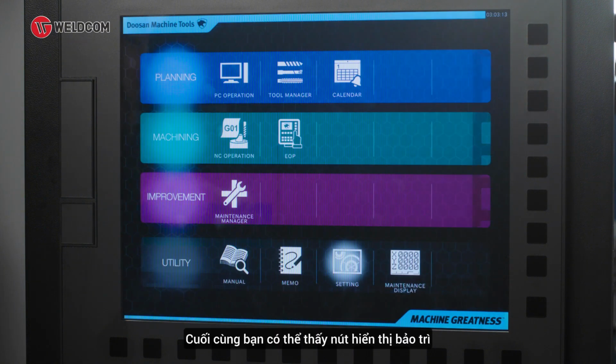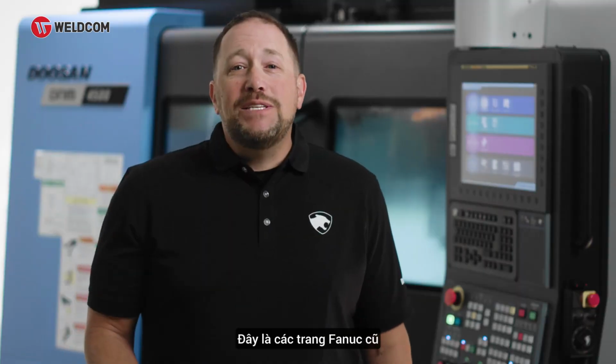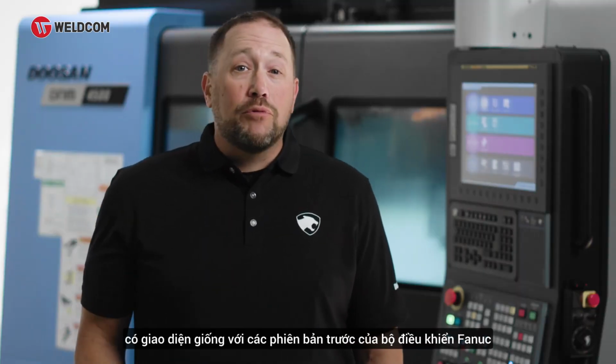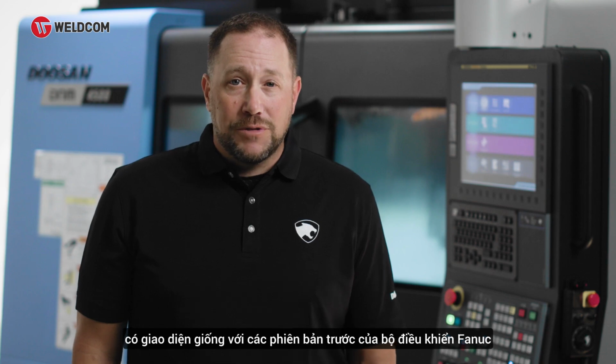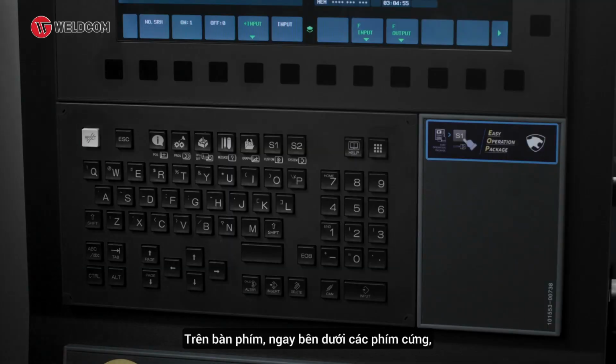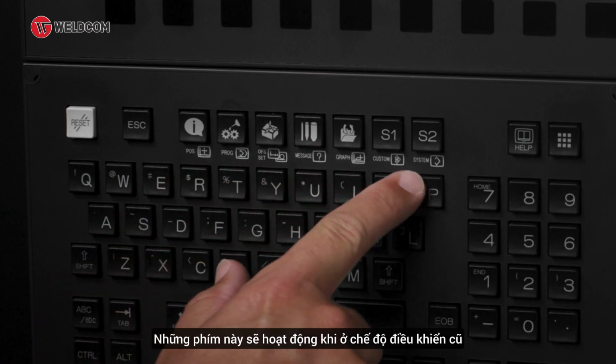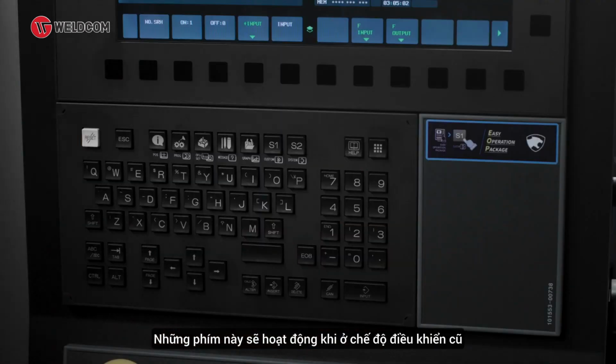Last, you can see the maintenance display button. This is where you can access the legacy NC screens. These are the legacy Fanuc pages that look like previous versions of Fanuc controllers. So for accessing things like parameters, keep relays, or doing a full backup, this is where you would do those things as you have on previous controls. On the keyboard itself, you will see below the hard keys, written in white, the legacy hard key functions that become active while in the legacy side of the control.